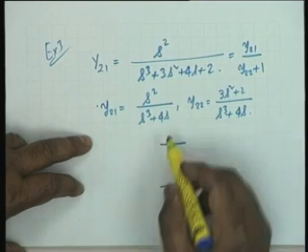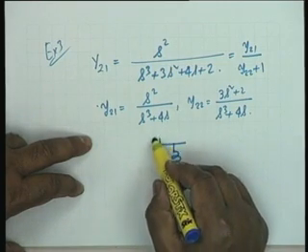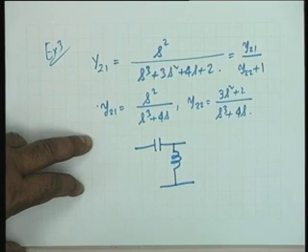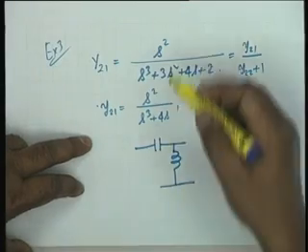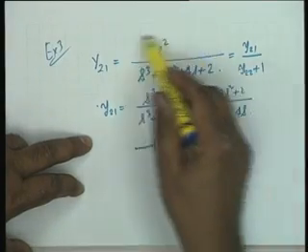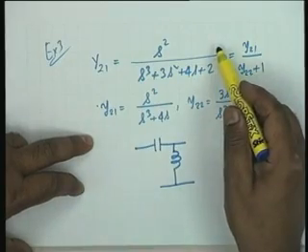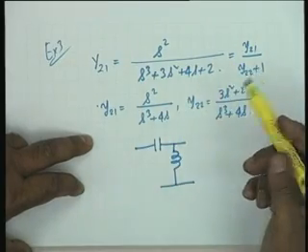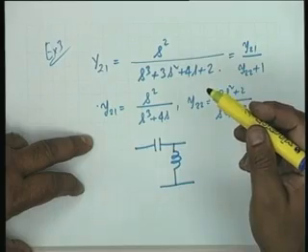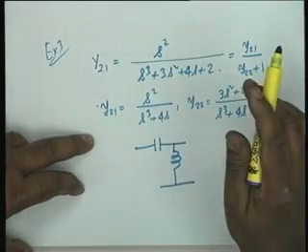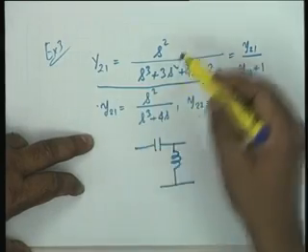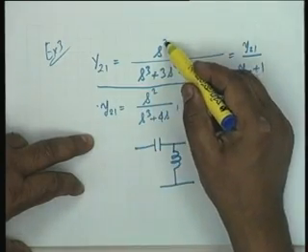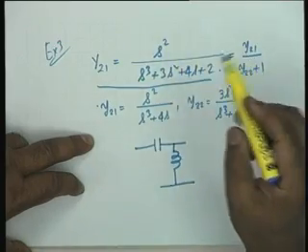and a capacitor in series. But how do we cancel the s out from the numerator and denominator plus Y21? Well, that does not change the transmission zeros. Transmission zeros are of capital Y21. We can do that, but that does not change the transmission zero. How are there two transmission zeros? Look at Y21, there is an s squared factor here, so 2 transmission zeros at the origin and 1 at